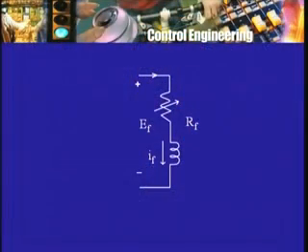One simple way in which one can provide for the field current to remain constant in spite of changes taking place in the power supply voltage is, of course, the following simple connection. You have the field winding, but in series with it you connect a resistor whose resistance is Rf, R for resistance, F for field circuit resistance.